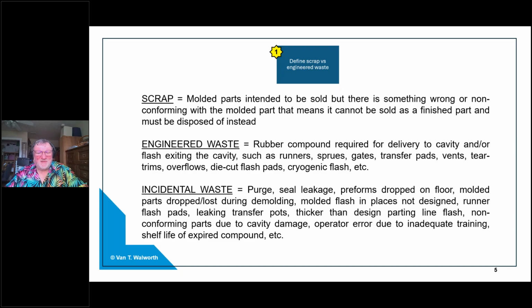of scrap parts, and then they'll say, well, now it's time we need to go out and fix the mold so that we can do all the cavities when we're molding. But in the meantime, all of those cavities have been scrapped. I mean, it starts out 10% if you've got 10% of your cavities that are damaged in some way. And so that's sort of a reason maybe to have designed your molds with removable cavities so that you can replace one cavity rather than having the cavities cut into steel where you can't remove one cavity and replace it very well. And things like that.